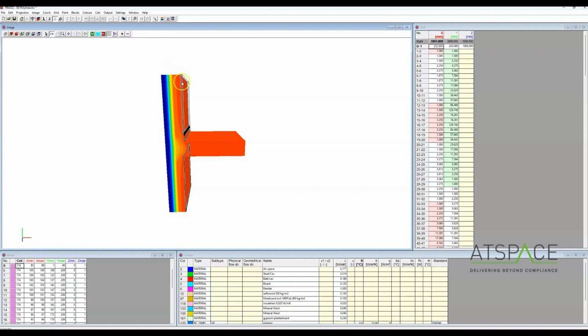But because we've set it to a certain length, as we set it to 1 meter earlier, for each flanking element, we can subtract the heat loss from those flanking elements from the overall model, and then what we're left with is just the heat loss from the junction, which is essentially what the psi value is.